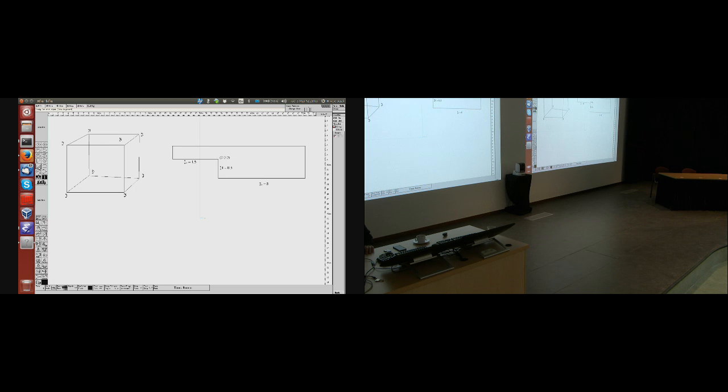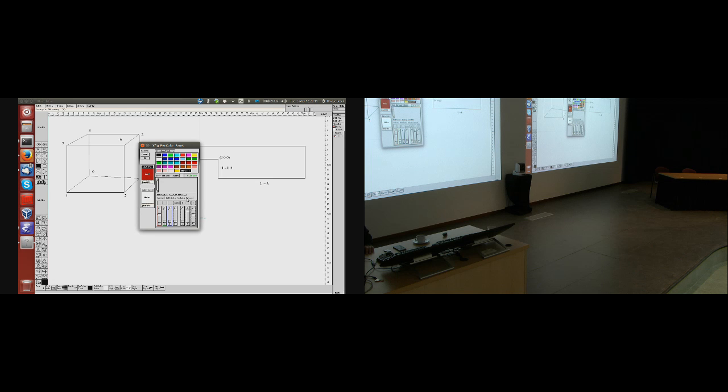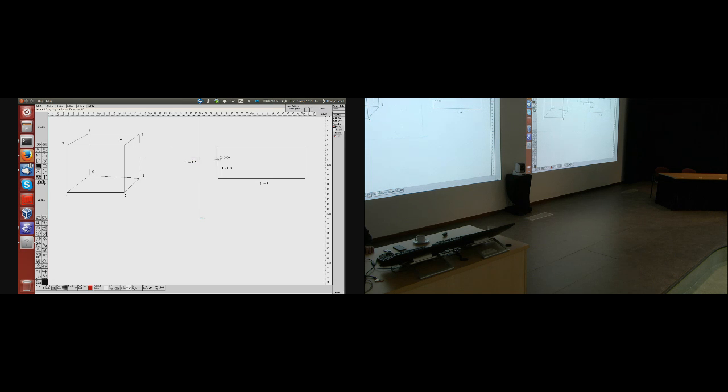Okay? In terms of the block structure, I can only define the blocks that meet face to face. Okay? So my block number 1 will be this one here. Block number 2 will be this one here. And block number 3 will be this one here. Okay? So to define my points, I will start counting from 0 and go 0, 1, 2, 3, 4, 5, 6, 7, and then you're going to have another plane of points like this, right?